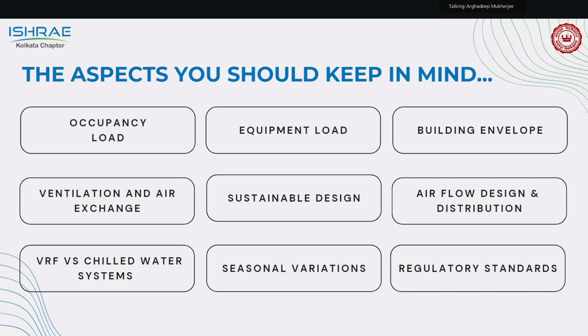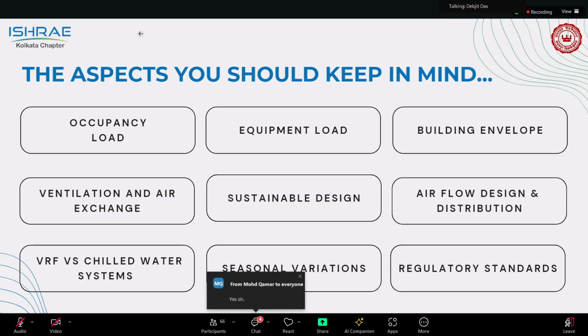So whether you should use refrigerants to cool the air, or should you use chilled water systems, because hospitals as it is need a lot of water for other requirements as well, like washing of different equipments, surgery equipments. Water is used for a lot of other functions in a hospital, because you need to maintain the cleanliness at the peak.